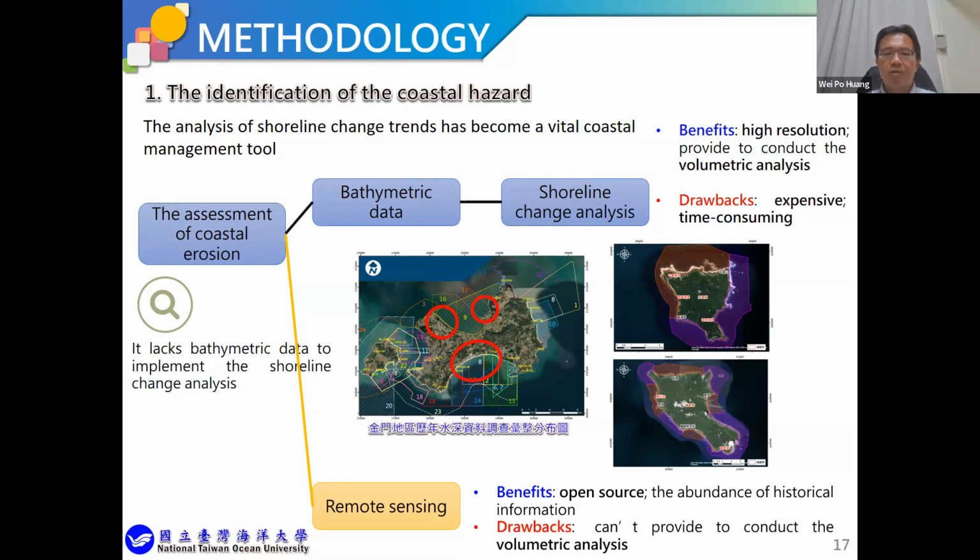However, a notable drawback is its limitation in facilitating volumetric bathymetric change analysis, posing a challenge in obtaining a comprehensive understanding of coastal changes. Furthermore, it's crucial to acknowledge that shorelines obtained from satellite images are influenced by tidal elevation, and for the sake of systematic comparison should be adjusted to the 0-meter isobase. This modification ensures a consistent baseline for evaluating and analyzing shoreline changes.